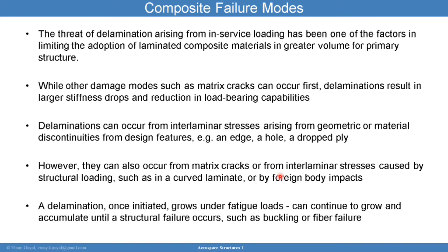Delaminations also are a problem, like I said before. If you left a piece of paper between 2 plies, those are initiation points for failure. But they can also occur from interlaminar stresses that arise from geometric or material discontinuities, particularly from design features such as edges, holes, and drop plies. However, delamination can also occur in curved laminates, and they can occur during impact damage events.